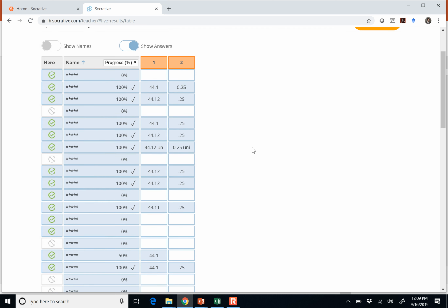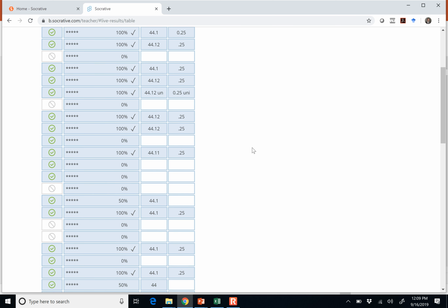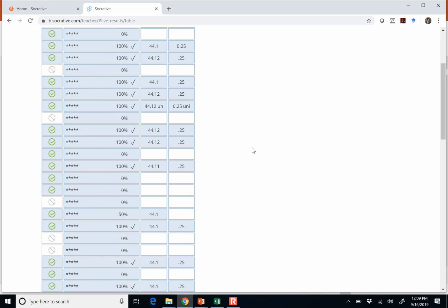Okay, pretty good. The oak wall has a Biot number of about 44. So would you apply the lumped capacitance approximation for the oak wall? No, it's much greater than 1, 44 times that. So pretty clear, pretty easy. Then the steel wall, in this particular case, has a Biot number of 0.25. So would you apply the lumped capacitance approximation to the steel wall?